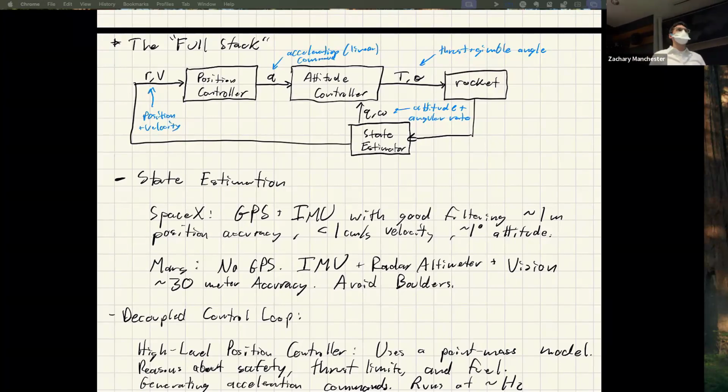Are there specific common failure modes for the initial soft landing problem? To be honest, I haven't looked super hard at this. I think it's pretty benign. If you wanted to do this with the full dynamics and just do nonlinear MPC, I'm pretty sure that would work pretty well, and you could do it, to be clear. But the thing here is that this has all the guarantees. You can say all the things about it you want to say, and it works really well. And you can solve what ends up being a pretty modest size SOCP at really high rates on an embedded computer.